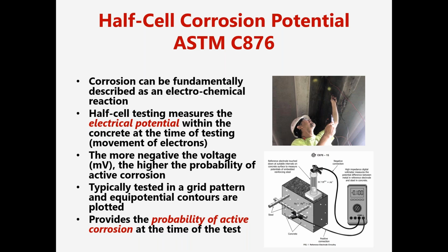This other electrode is attached to the concrete reinforcing steel. One of the things we always make sure of whenever we're doing this half cell testing is that the reinforcing steel is all connected, electrically continuous. So we'll expose reinforcing steel, maybe in the top right corner or northwest corner, and then in the southeast corner.